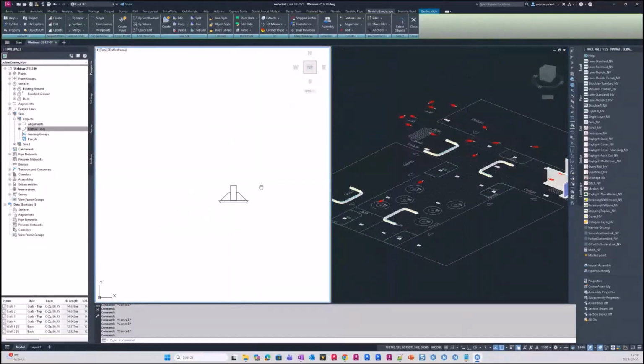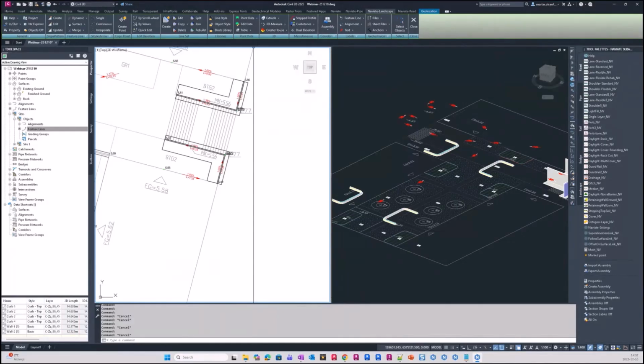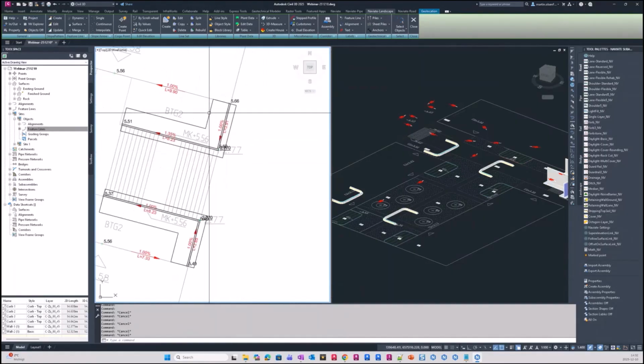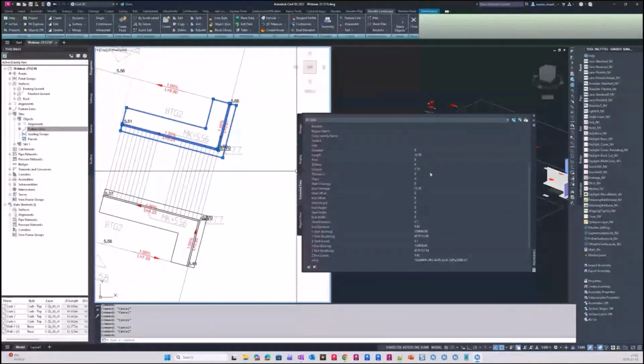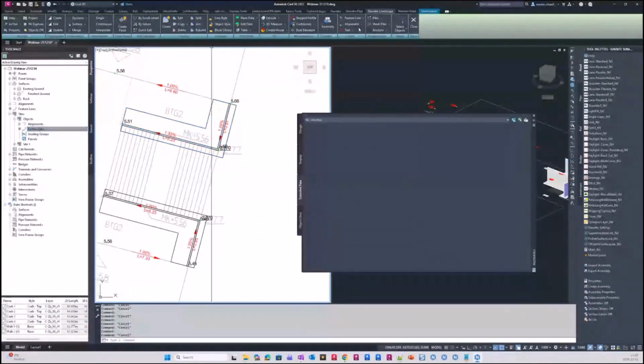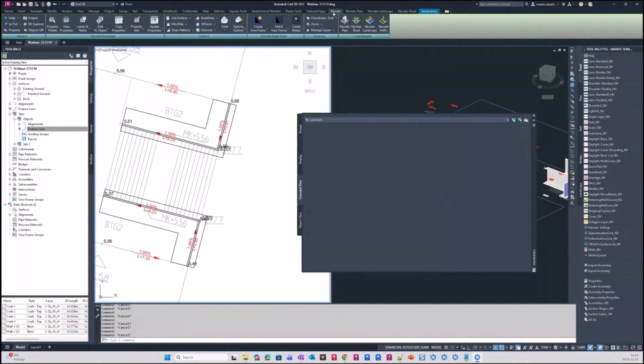So let's continue here. Great. That's about the extrude function. And if you remember, I also added some property sets on my retaining walls. And it means that we also got this data on the walls now. So if I want to do a takeoff or just be able to search for my retaining wall, I can use the Naviate property palette here.